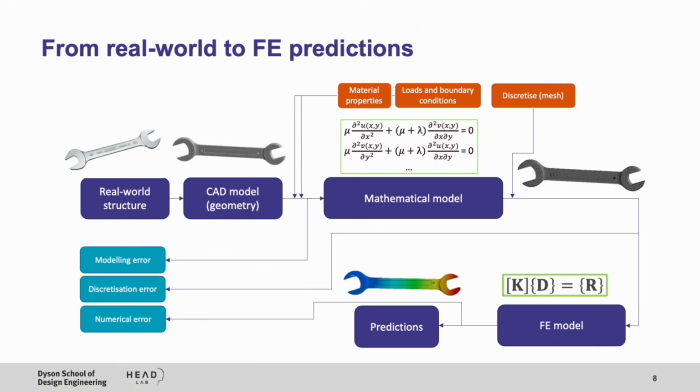And often these finite element packages like Elastica, ANSYS, Abaqus, etc., come with the choice. So you can choose if you want single precision or double precision, which has a certain meaning in every software, so you need to be sure that you understand what the package is referring to. But really, when you move from single precision to double precision, it means that you're using a bigger unit for holding a floating point variable, and therefore what you're holding in memory is more precise, but it also means you need more memory and more computational time for the model.